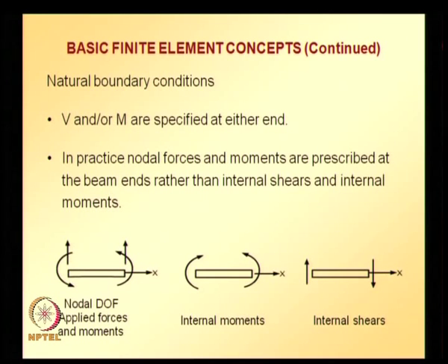If you go back and see the sign convention that we started out with, the first figure shows the sign convention for nodal degrees of freedom, that is transverse displacements and rotations, and also the sign convention for applied forces and moments, whereas internal moments and internal shear are given in the second figure for internal moments and the third figure for internal shear.